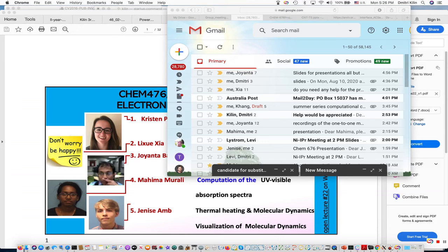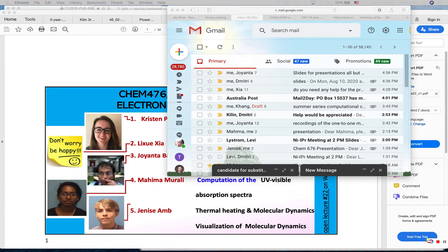Hello everyone, I'm Lixue Sha, a visitor of this course, and today I will give a brief review of DFT input files. As we all know, we need 4 files to complete a VASP calculation, including the INCAR, POSCAR, POTCAR, and a script to submit the job.